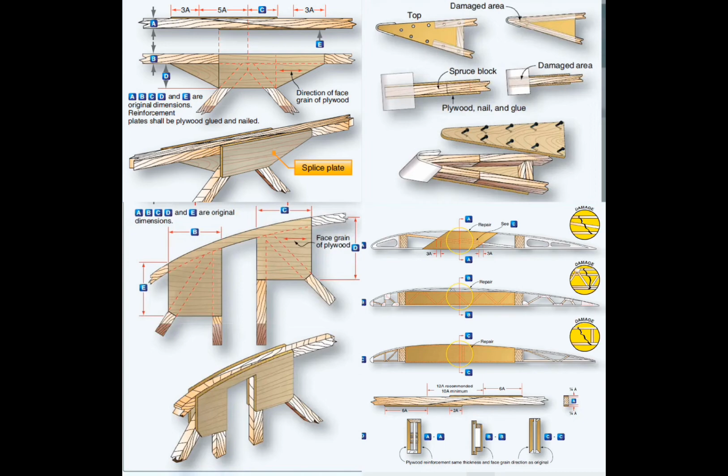Are knots allowed in aircraft wood? Within limitations: type of knot, location, spacing, and number of knots. What type of wood quality must be used in the repair of aircraft structures? Equivalent to its original strength or greater.